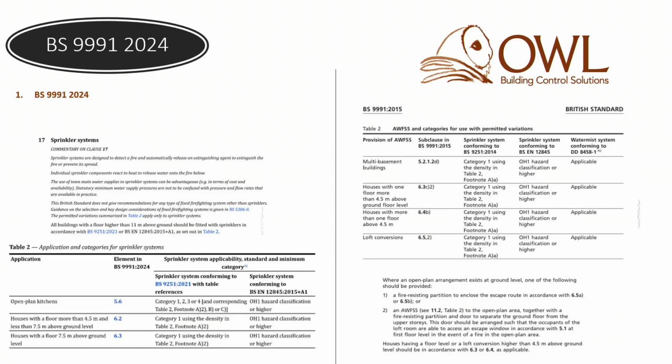So the concern is that if that misting head is retained and there for 15 years, and it's been hardened, then the actual calcification of that misting head will result in it not being able to be fit for purpose in the event of a fire.